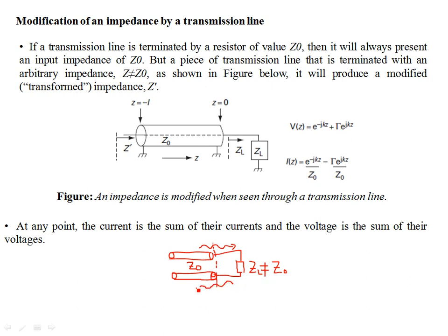Some of the power is reflected back to the transmission line, and it forms a standing wave pattern. As your VSWR, the voltage standing wave ratio, increases and approaches infinity, you are losing the power. If the ratio of the maxima to minima of the standing voltage amplitudes reaches infinity, then you're not transmitting any power to the load. So you need to design an impedance matching network here at the interface.